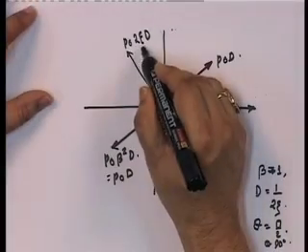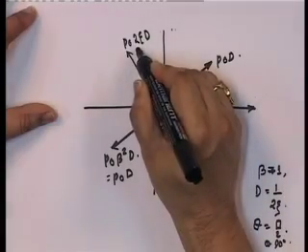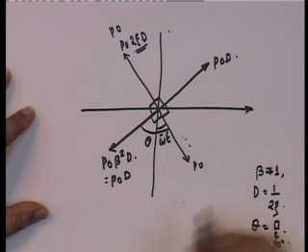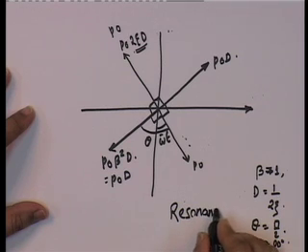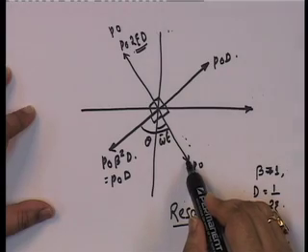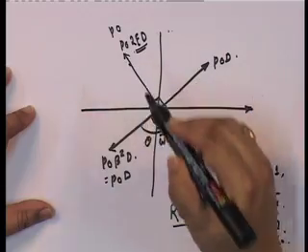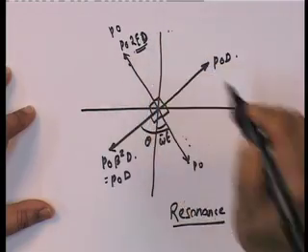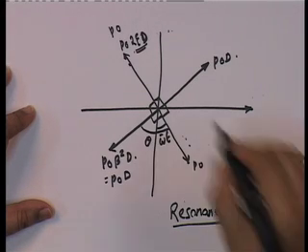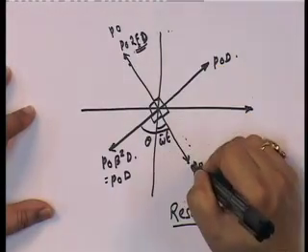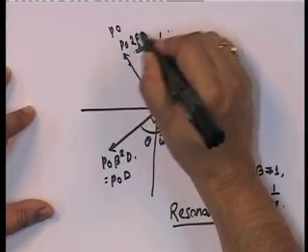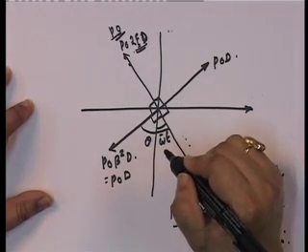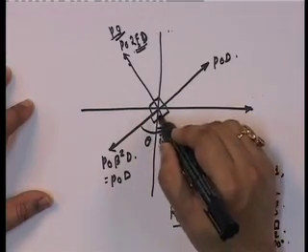Look at the very interesting thing, and look at what d is. D is 1 upon 2 xi. So if I look at this, what does this become? This becomes P naught. Look at this very interesting thing: at resonance, when beta is equal to 1, the applied load is resisted completely by the damping force, because it is only resisted by the damping load. That is the reason why the dynamic amplification factor becomes 1 upon 2 xi, very large. If damping is low and it has to resist this, dynamic amplification has to become 1 upon 2 xi, so that this becomes P naught, and it can resist this. And look at the inertial force and the elastic force. They are completely out of phase, sorry, not out of phase.